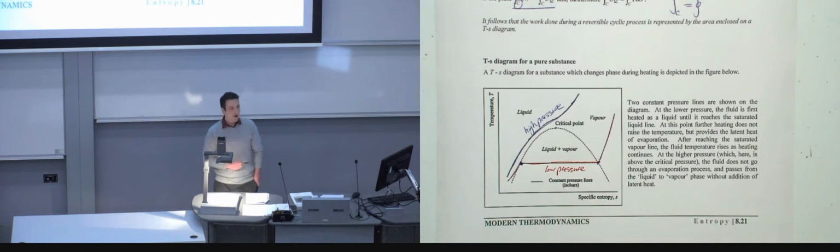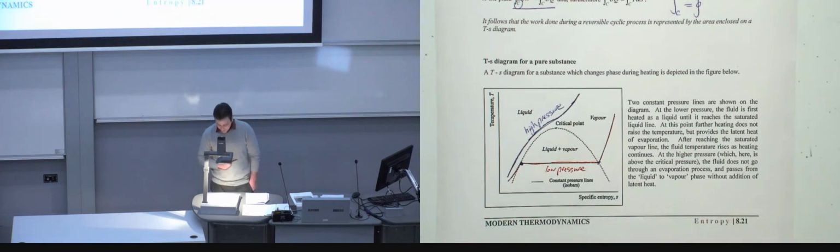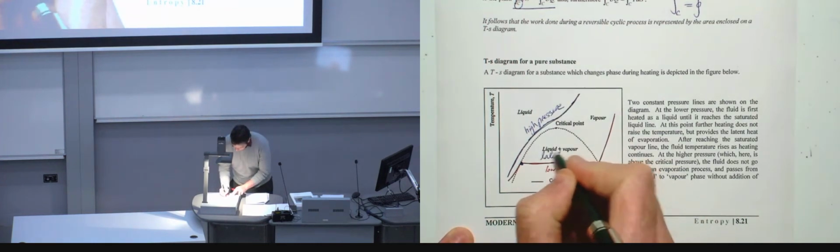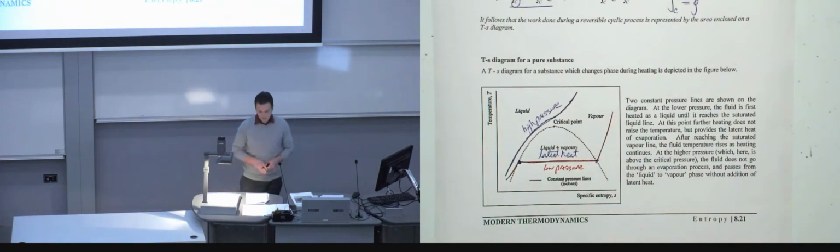The temperature is not going to rise because you're changing the phase of your liquid from liquid to vapor. So from water to vapor, that happens here. Therefore, you have latent heat. And then once you get to that point, when you've got dry saturated vapor, then you start heating up again and temperature goes up and it becomes superheated.